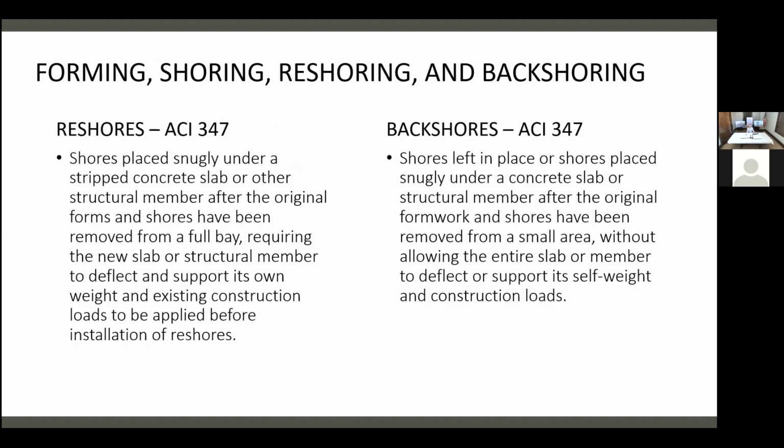So I want everybody to understand ACI 347. My older brother sits on this committee, and this covers reshores and backshores, which not all engineers understand. Basically, if your slab cannot be self-supported, you need backshores. Backshores need to be left in place and load accumulates down your building, which is a huge thing, because there's a lot more backshoring and shoring needed at those lower levels because the load is accumulating down the building.